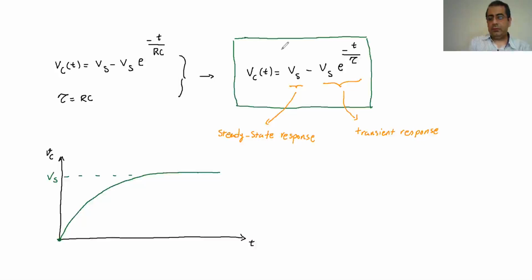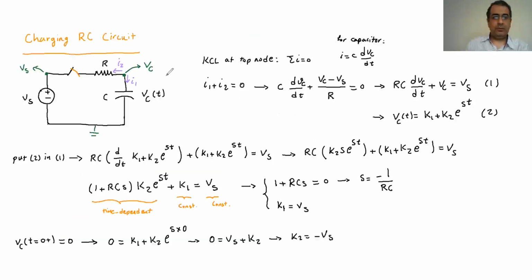So very quickly, if I want to go over what we talked about: assume the capacitor is completely discharged, and we want to charge it. To charge it, we connect it to the resistance and the battery. As soon as we close the key, the battery starts to charge the capacitor.